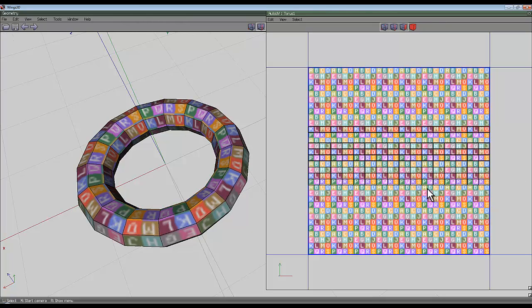You can't loop an open end in here, it doesn't recognize that as a loop. So if I select that and press L for loop in this view, it won't extend. It'll extend one here because that is a loop in this view. It's a bit weird, but that's just the way it works.